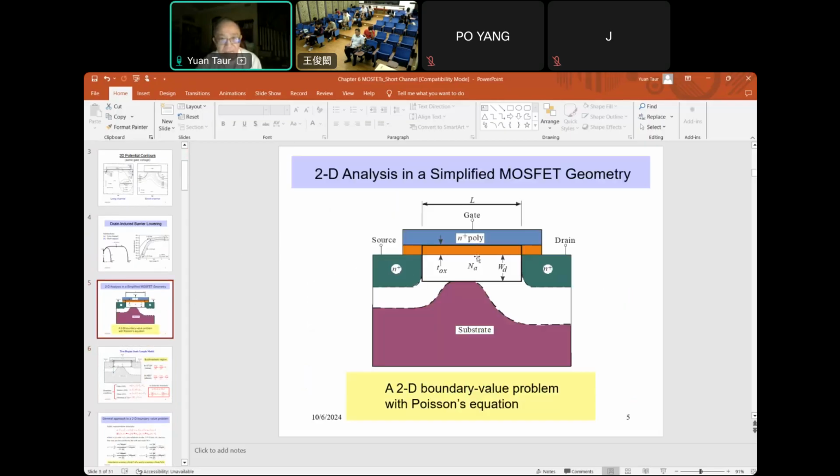So this is a two-region model, but if they have the same dielectric constant, essentially it is one region. In that case, the lambda is basically the height of this rectangular box, WD plus Tox. And the minimum channel length is twice the height. So L minimum is 2 times WD plus Tox. In other words, the aspect ratio of this rectangle determines the severity of the short channel effect.